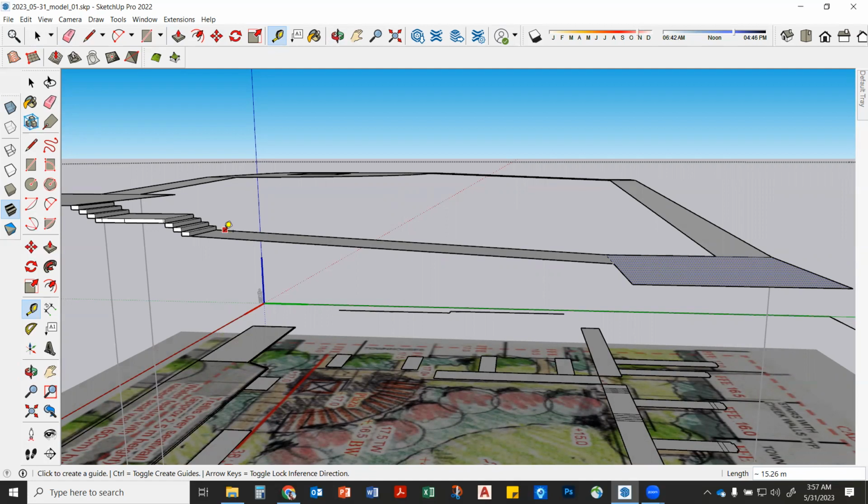Okay? This one, once you build your steps, build them here, and then go build your stairs here, yeah? Build both sets of stairs. If you're waiting for me, yeah. If you're not waiting for me and you're just getting your stairs done, you can do it, all right? And then if you have a little bit more time, tell me what percentage slope these are. And if they're under 5%, good. If they're over 5%, you might need to add a landing. Drop the slope, right? So.